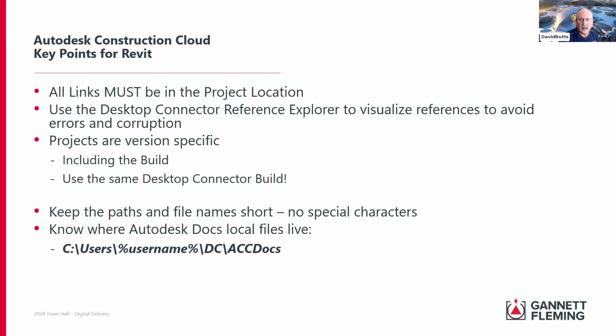And I'm a big overlay guy. I don't use attachment as much as I used to, especially since I started not using AutoCAD Architecture as much, where attach was really great for setting up constructs and elements and views. That process worked really well, but in Revit, it doesn't work as well. You're better off using overlay most of the time.